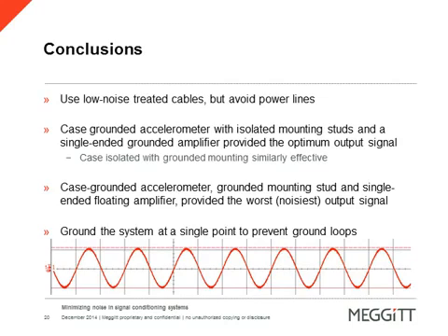So today we have discussed various noise sources, including capacitively and magnetically coupled noise, and how they adversely affect vibration and pressure measurements when not addressed properly. Understanding the possible sources of noise, ground schemes, and proper installation techniques will optimize the test and measurement process.